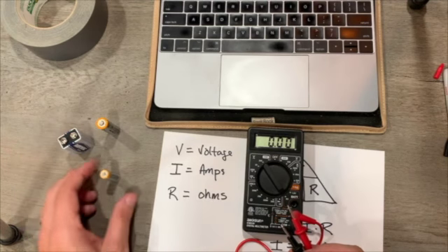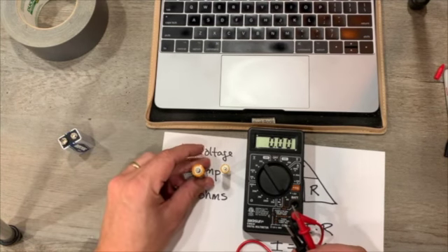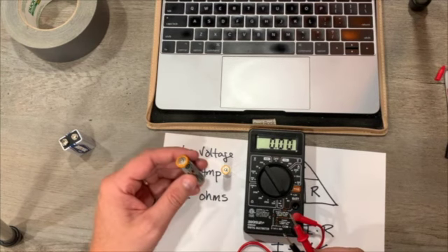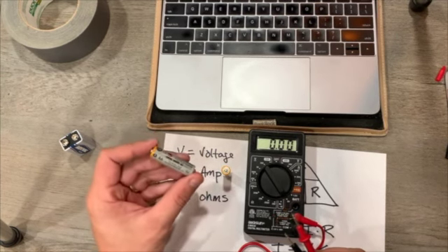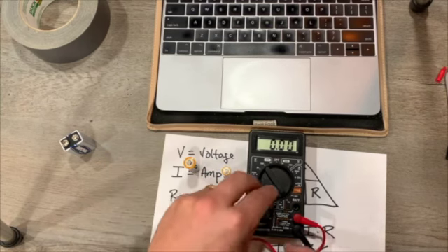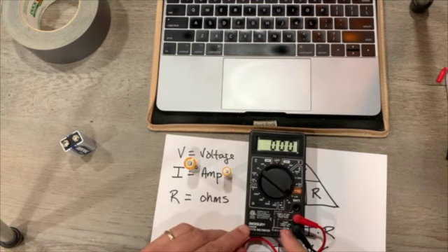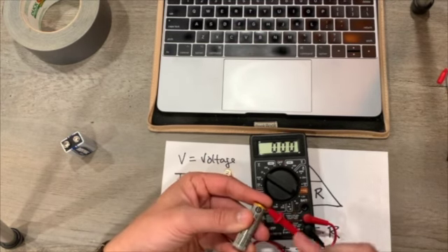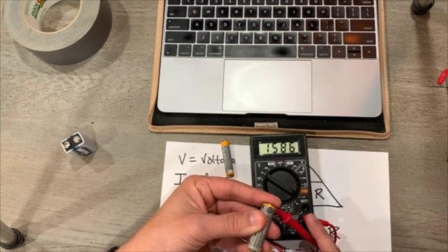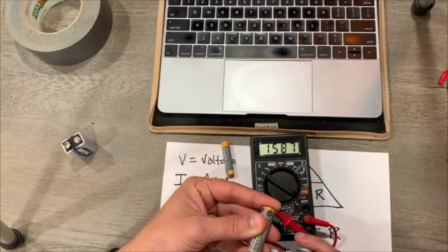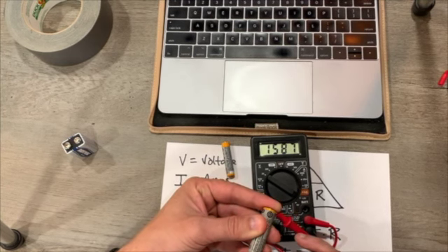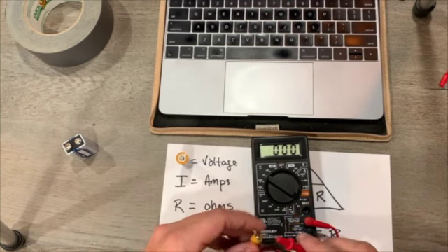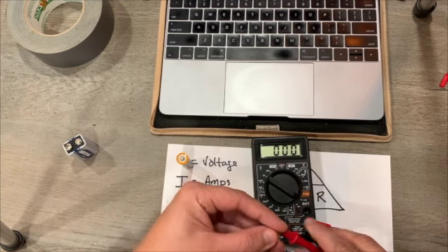A couple of others, I have a AAA battery and a AA battery. Now, you might be thinking that one of these is a higher voltage than the other. In fact, it is not. They are the same voltage, and we can test that as well. I'm going to switch it here to my 1.5 volt option, and then again, hooking up the lead of the positive to the positive and the negative to the negative. You can see the readout here showing that we are actually a little higher than 1.5. So, 1.587. And then let's try our AAA, positive to the positive and the negative.